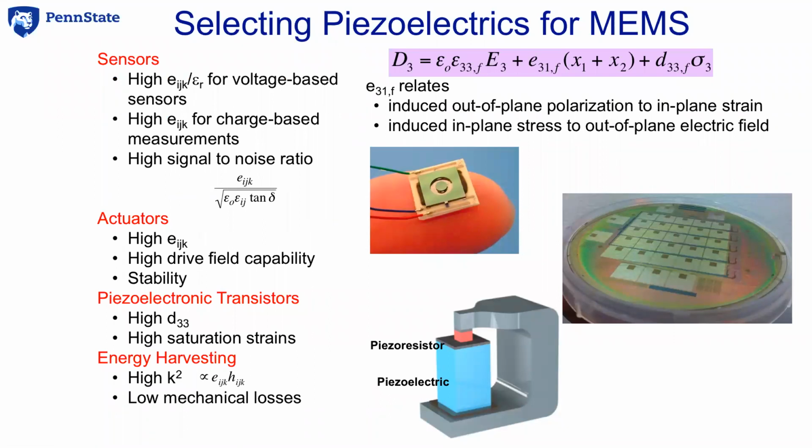Unfortunately, however, the piezoelectric coefficients of those materials really are very modest. And we can see that if we think about the key piezoelectric coefficients for a microelectromechanical system. One of the characteristic features of those systems is they tend to utilize thin films. Most piezoelectric materials will strain limit between 0.1 and 1%. And so if I only have a thin film that's a micron thick, I don't get much absolute displacement from that film unless I use a mechanical amplification system.